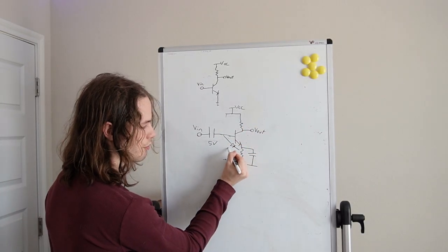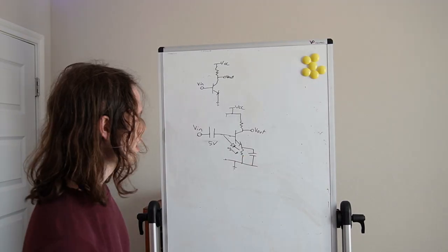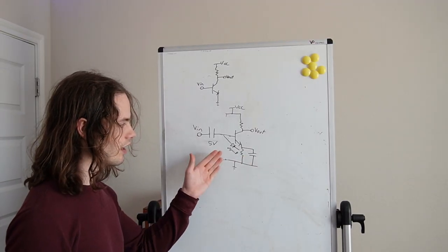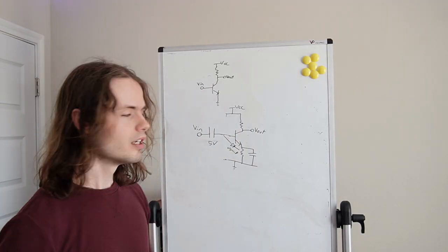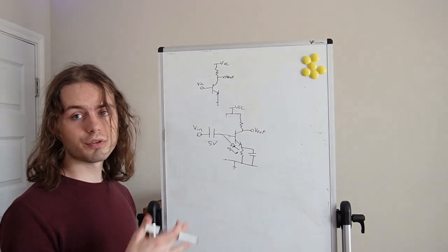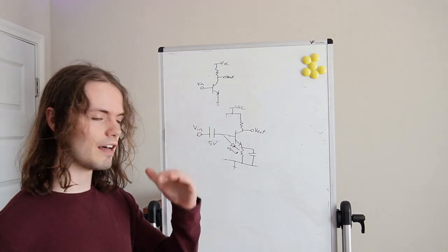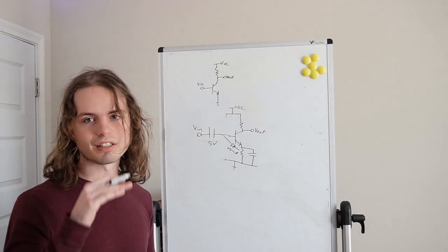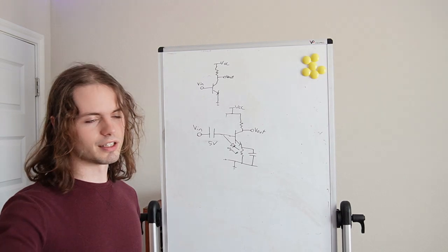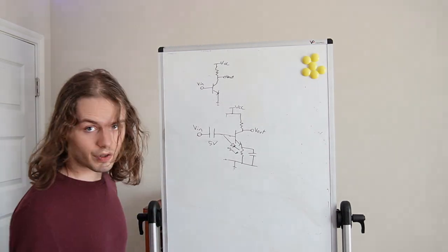So this is around 0.5 to 0.8 volts, somewhere in that range. And unless you exceed that voltage, the output is not going to show anything. So you're going to be losing a good chunk of your signal. It depends, again, on what level your voltage is. But in the end, you'll lose the entire negative portion of your wave and some portion of your positive. So that is if you just directly connect it.